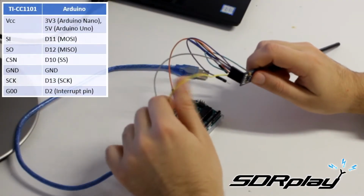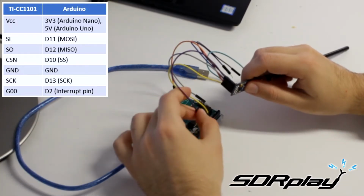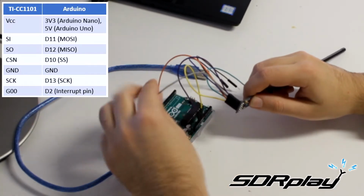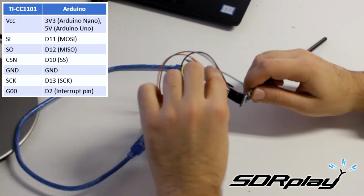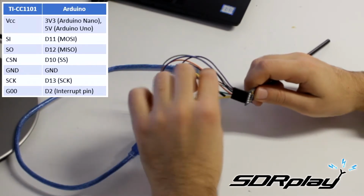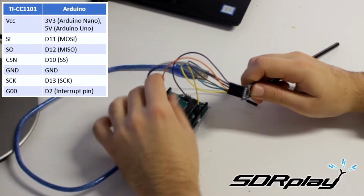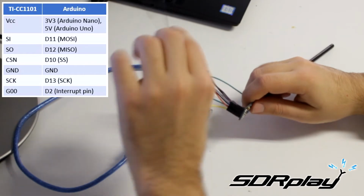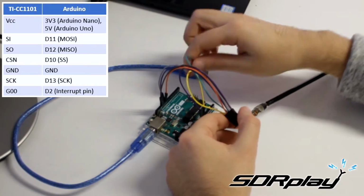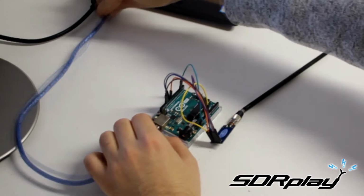We connect the ground pin to the ground pin of the Arduino, the power to 5 volts since we're using an Arduino Uno, and then slave input to D11, slave output to D12, chip select to D10, clock to D13, and interrupt to D2. We can then connect the Arduino USB to the computer.